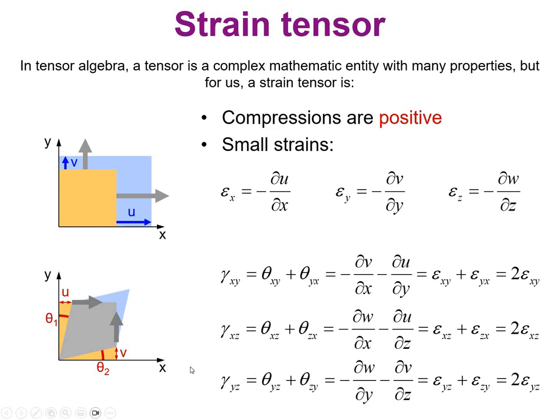And you are going to have distortions that are defined in this graph in here, distortions because you apply shear forces to the elements, the cubic element we have defined at the beginning of the presentation. And these are the mathematical expressions as partial derivatives in terms of the displacements in x, y, and z direction, and the derivatives with regard to x, y, and z, which are the orthogonal coordinate system we have defined at the beginning to work with.